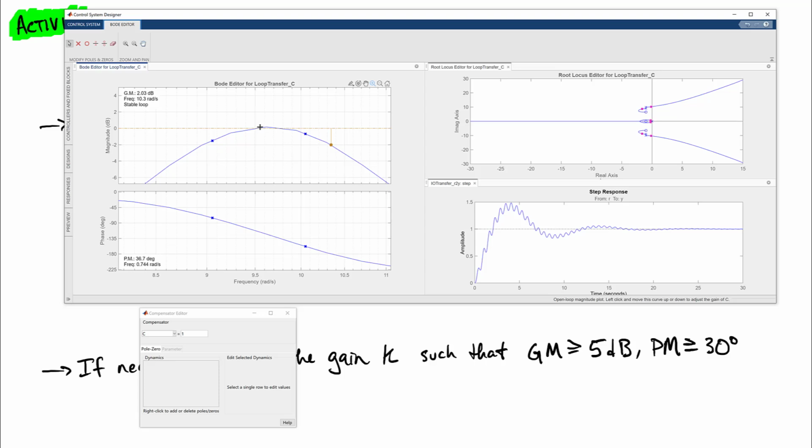And so those are happening real close to each other. And so those would give you 2 more phase margins to investigate. And so if we look at what the phase margins there would be, we can see that these values are going to be roughly around minus 135. So it's a bigger phase margin than what is being quantified at this lower frequency value.